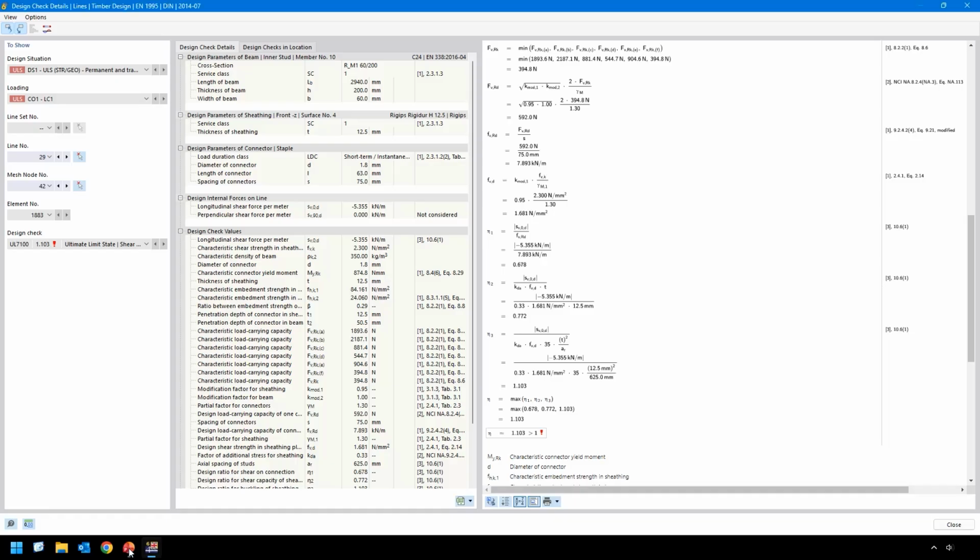And therefore, we need to consider these additional forces by using this factor 0.33. This factor is really low. There is some research in Switzerland about this factor, and they found out the value nowadays is higher. For OSB 3, for example, the factor here would be 0.85.